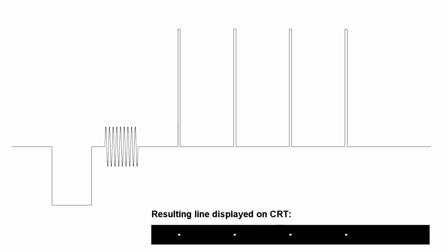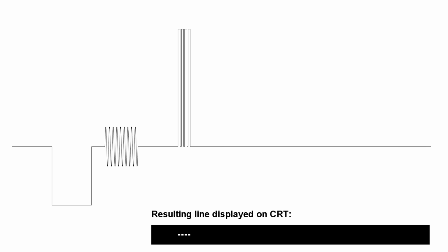Consider this black and white screen, where we wish to represent pixels so small that luma goes up and down very quickly. In other words, the luma frequency gets very high. So high, in fact, that luma becomes indistinguishable from a valid chroma signal. Remember, the chroma frequency is always 3.579545 MHz. If luma horns in on that frequency, the TV will misinterpret the brightness changes as a valid chroma signal and will generate color as a result.